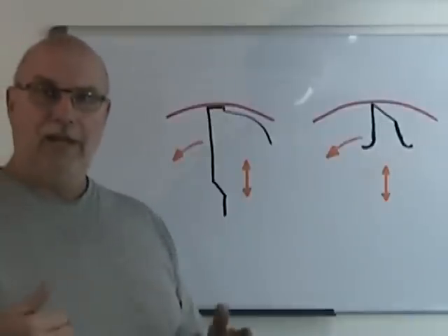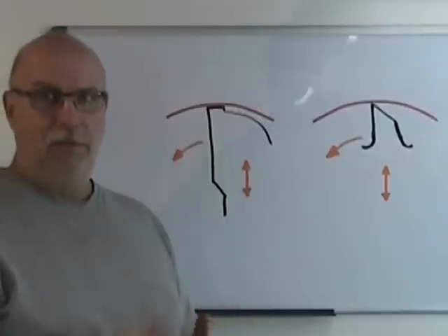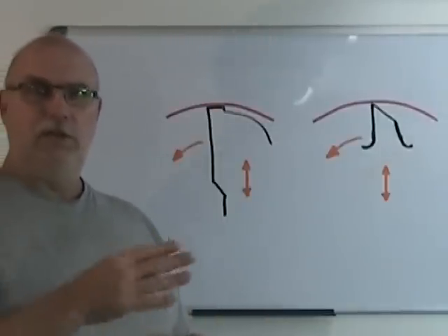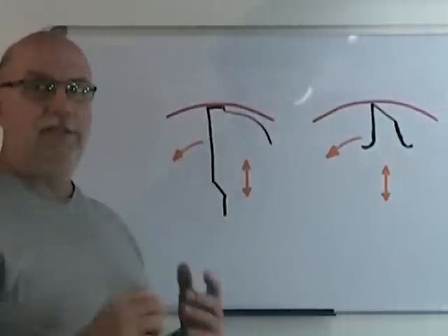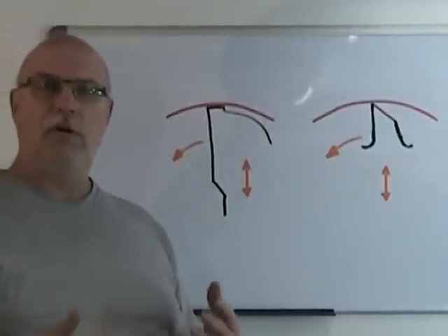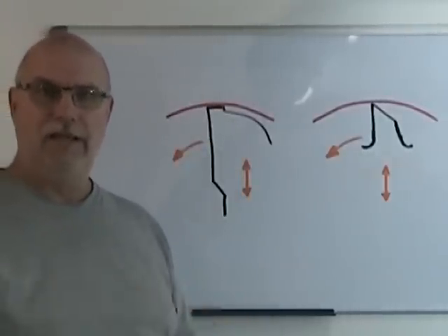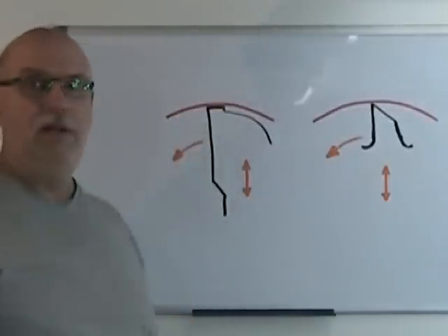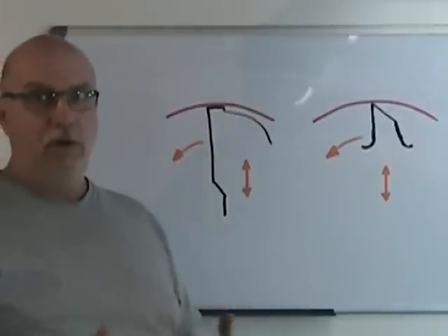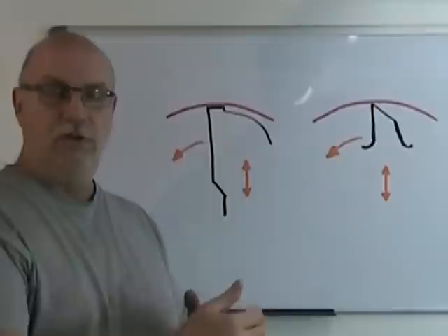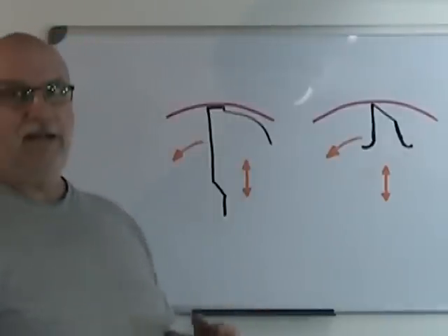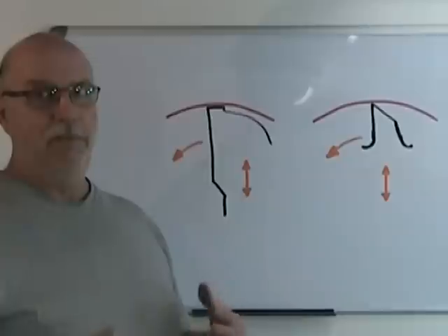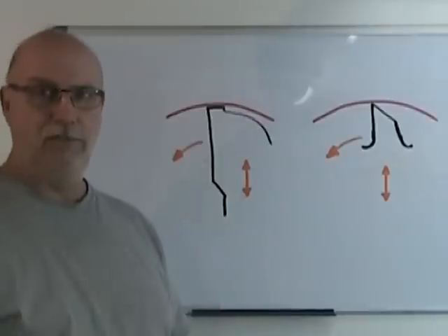We want to retract the drill rapidly from a deep hole, as rapidly as possible. Not because we're afraid that chatter on the margin is going to enlarge the hole. It's more a question of keeping the temperatures down due to friction. And obviously these rounded margins do rub, especially when you're retracting and inserting into a deep hole, and that creates a lot of heat. So to avoid that heat, I recommend you pull a tool out as quickly as possible.